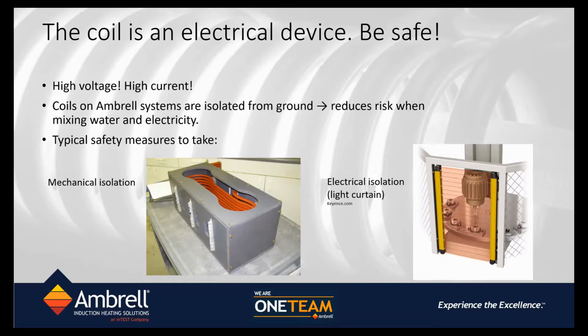If you're in the vicinity of the induction heating coil, working around the coil, you have to make sure that you have typical safety measures of either having mechanical isolation on the coil so you can't get too close to the coil, or have electrical isolation built in, like light curtains or light switches, so that if somebody tries to reach in and get in the vicinity of the coil, then the induction heating power supply can turn off.